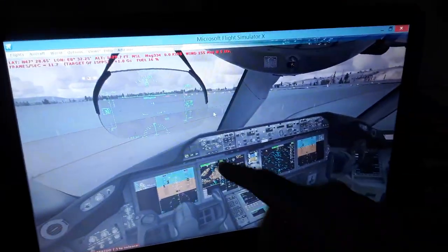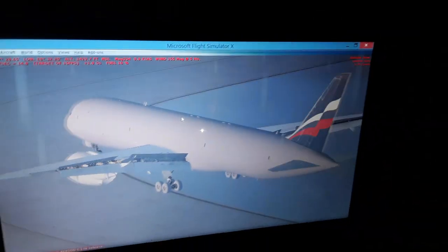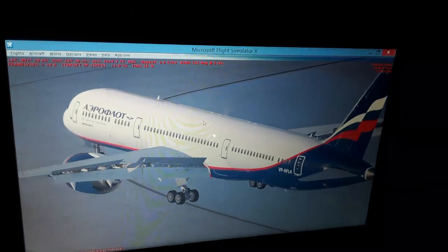We have also the flight mode annunciator with the autopilot and the autothrottle, lateral and vertical navigation modes, the radio altitude above the ground level, barometric pressure, and the HSI, the horizontal situation indicator that displays the magnetic heading and track, also the integrated display of the flight plan. So this is the aircraft I will talk to you about.